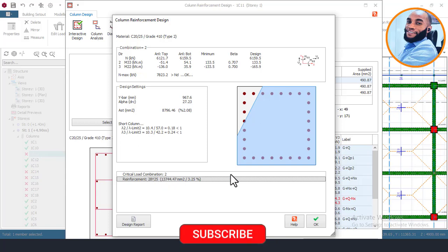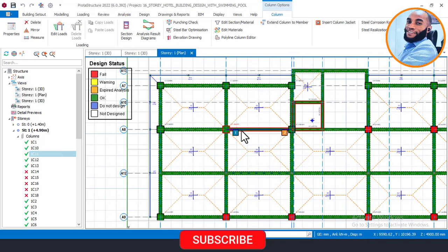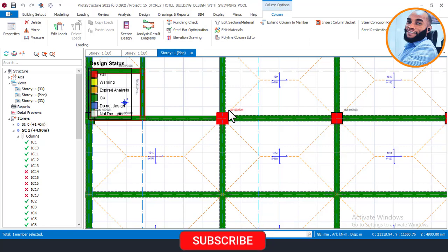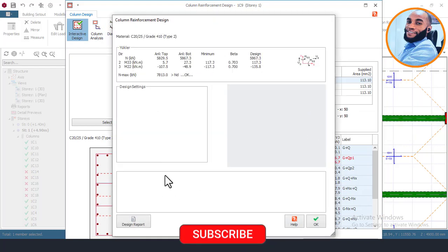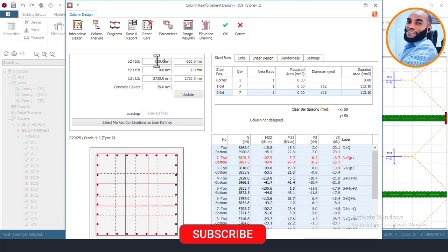So with this, I will now come here and click okay here, and then final okay here. That's fine, and the column now will be okay again. So just repeat the same process for all the columns that are failing. I'll come again and click on this to confirm and see why it is failing. Okay, I'll then say okay, and then increase my size here to 650 and 650, and I'll come here, 0 here, update.